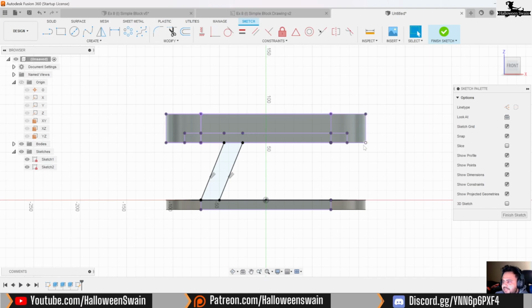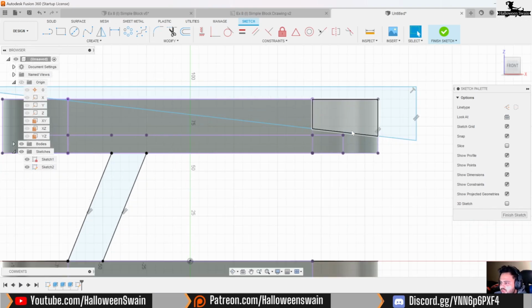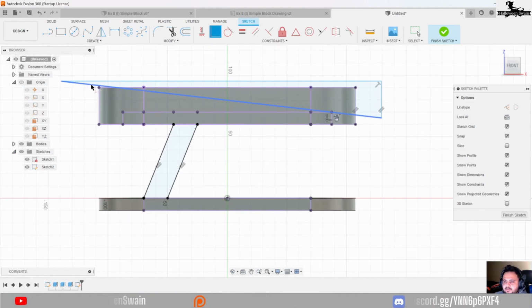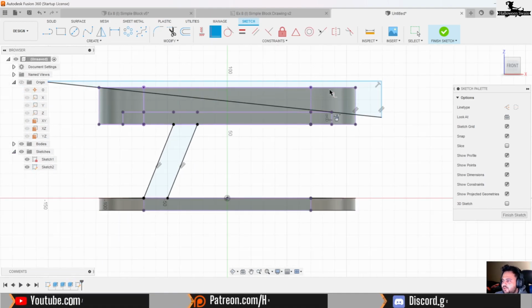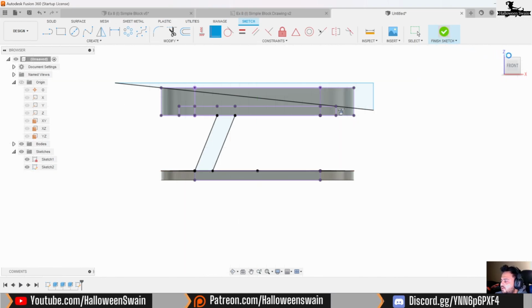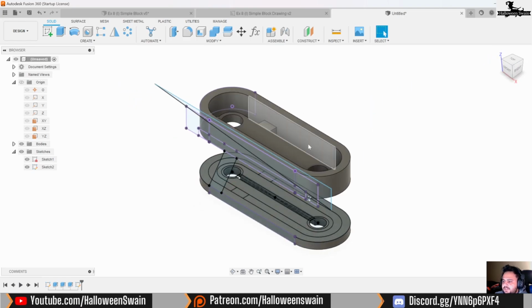So now we are going to make another triangle. So like this, and join. Now we have to make sure of two things over here: one, these 2 points should be coincident, and these 2 points should be coincident. So in that way, when we extrude the surface, it's going to cut the entire part. Here we go. So now we are going to start the extruding.